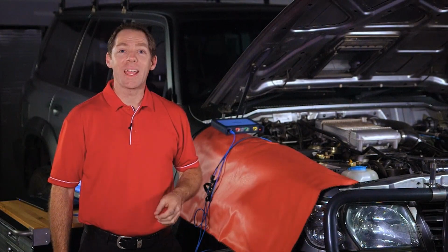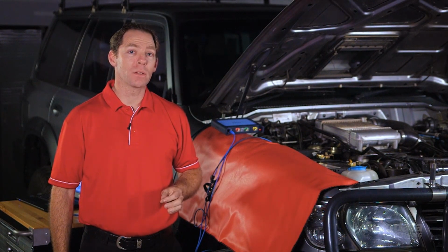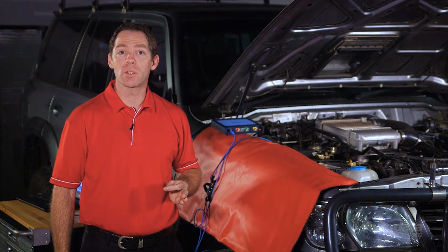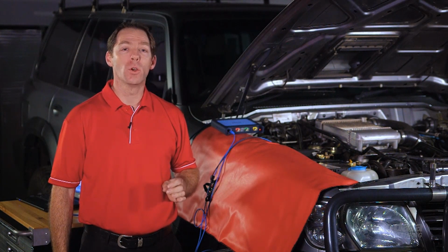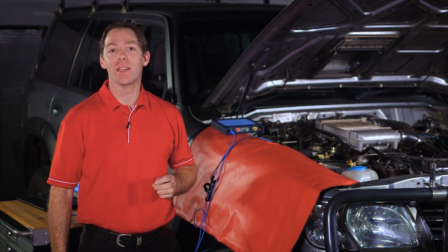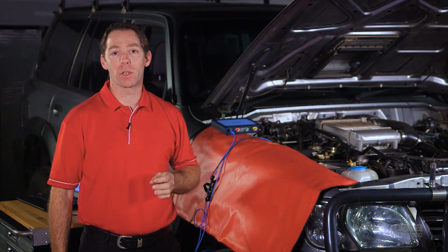If you have proved the electrical side of the EGR system is okay and your vacuum gauge readings are not, then the only fault at this point is a sticking EGR control solenoid. Generally, any faults in the voltage supply, control or position circuits will log system performance or circuit fault DTCs and not flow-related trouble codes. So far so good. If the electrical circuit and vacuum circuit are okay, we can move on to the EGR valve.